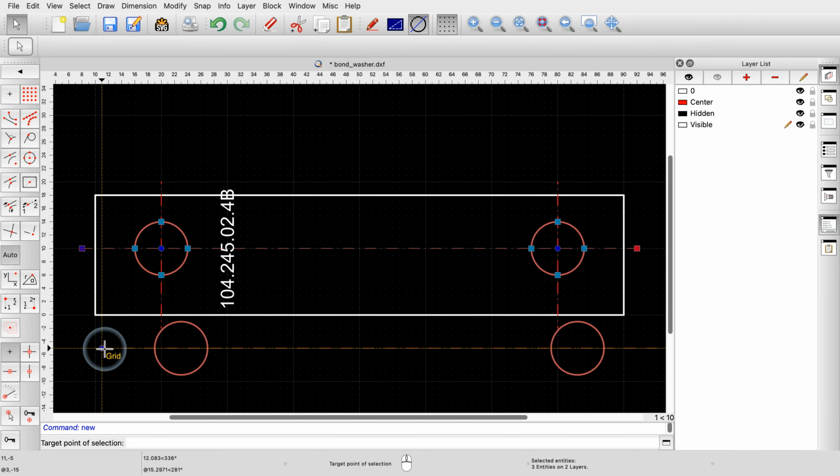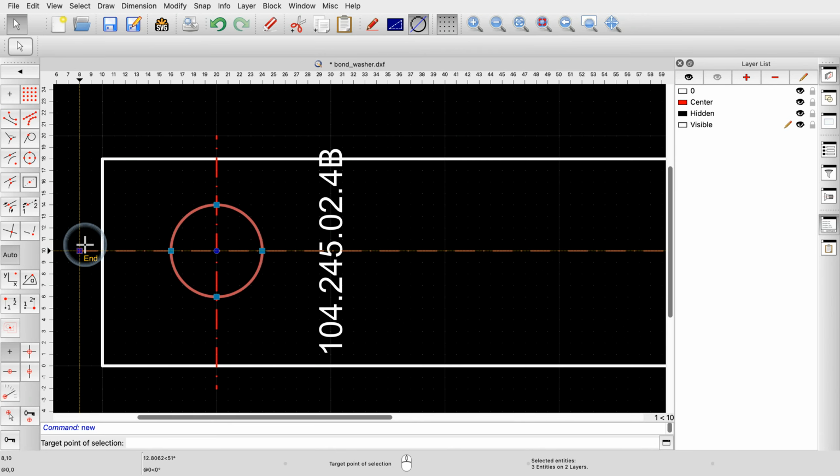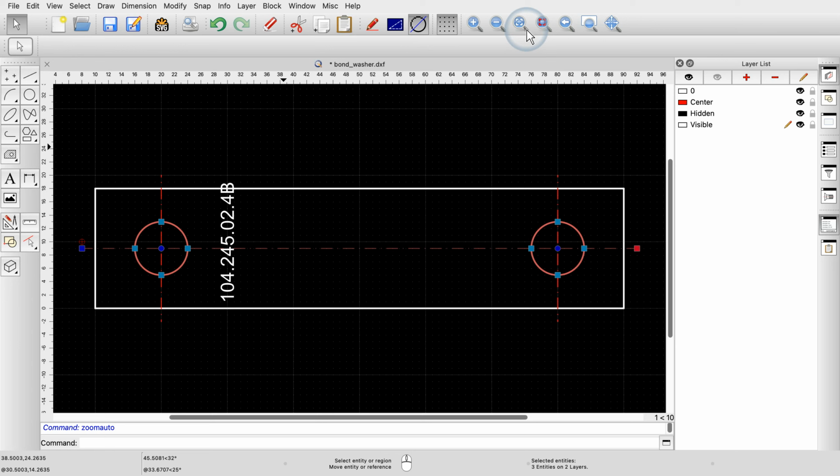For this example, we zoom in a bit first, to make it easier to place the selection. Now we click the left mouse button where we want to place the selection. AutoZoom brings us back to the whole drawing. This is how we can move a selection using drag and drop. To show an alternative way, we first click the undo button to reverse our change.